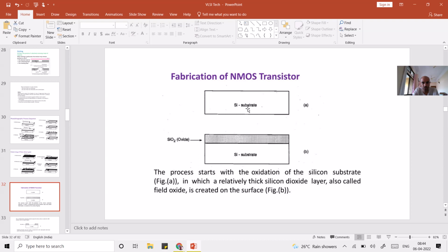If you put the 111 seed in the Czochralski process, then you can easily form the pure crystal. That is why, earlier, when ion implant technology was not invented and people were not able to fabricate MOS, the BJTs were fabricated and 111 worked very well.